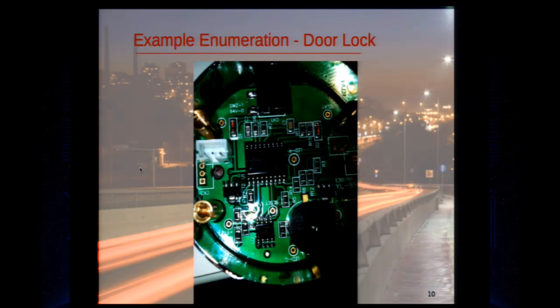All right, so I'm going to now talk about the things I wanted to try out, but didn't have quite enough time to. So this is a door lock example. Right here at the top is an emergency power jack, and I thought maybe this would be kind of neat if I could get a glitching exploit working on it. Unfortunately, there is this little capacitor right here, which kind of stopped me from getting successful with it. Given that I pried off the doorknob, if I were to try a glitching attack on it, it wouldn't have much point because this thing right here is the connector to the motor that drives the doorknob. So there wasn't really much of a point to do this example. And even if I did get a successful glitching attack off on it, it would be fairly difficult to build a rig in order to perform an attack on the doorknob.